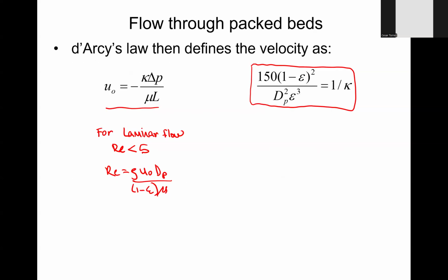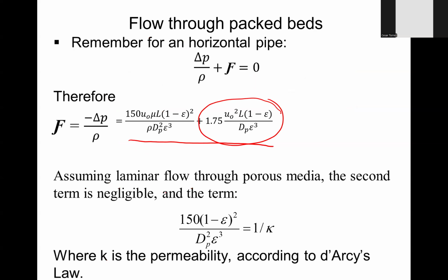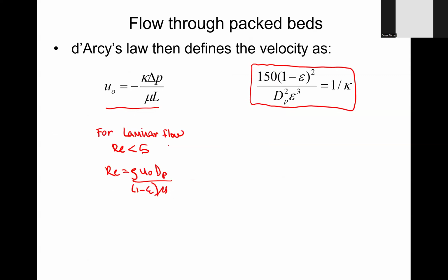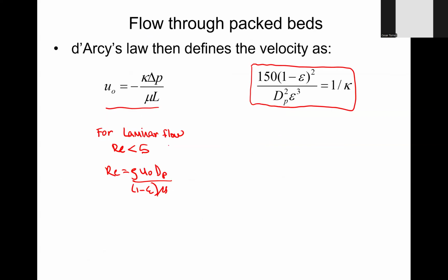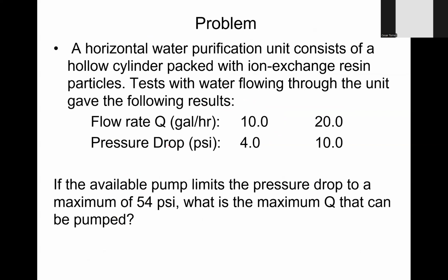So with these equations, the simple equation of Darcy's law, and then this longer equation, which is still applicable and can be used at any point, we typically have two types of problems or approaches to solve packed bed problems. And so I'll give you two examples of two problems and how they relate. Both of them, if I remember correctly, include turbulent flow, so the laminar flow equation will not be used. But you will see that they are rather simple to solve.